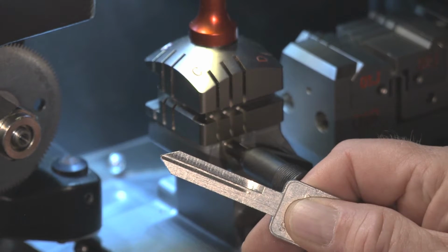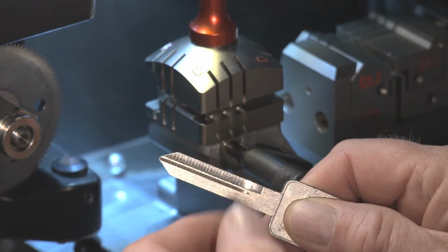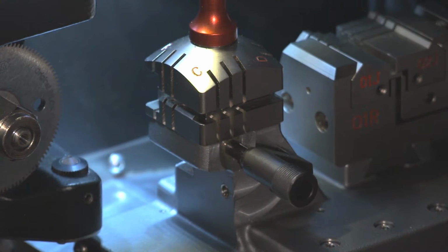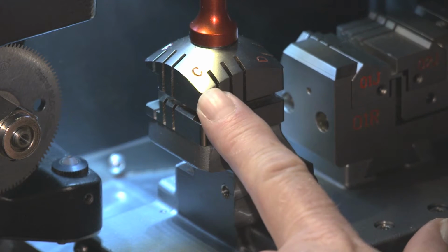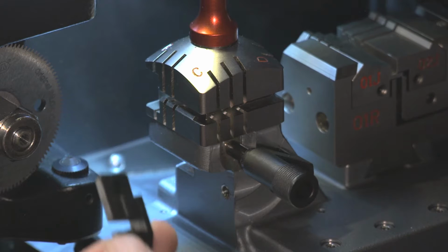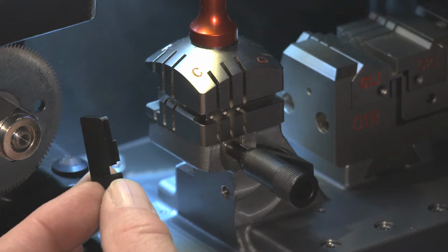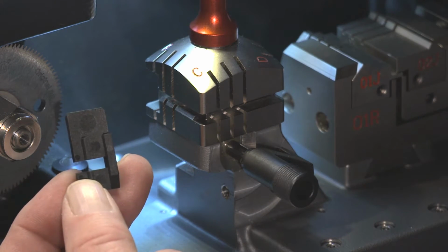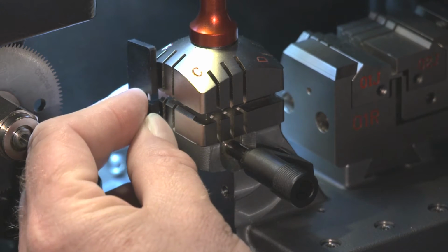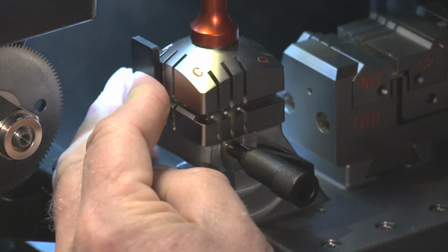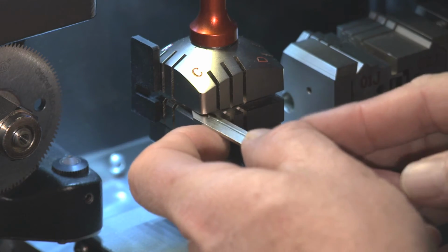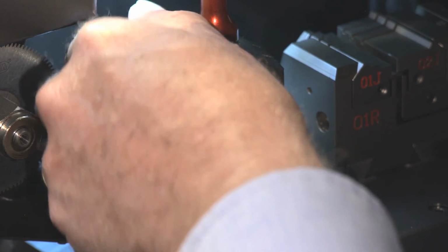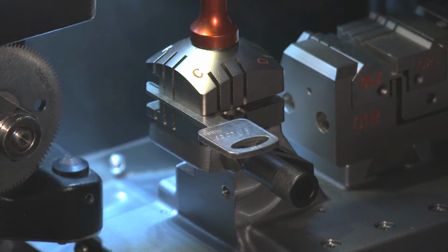Notice that with this particular key, the milling groove runs down the center of the blade on both sides, so I can use either side C or D. In this case, I will be using side C to clamp the key in the milling groove. Since this blank does not have a shoulder, it will be gauged using the tip of the key blade. The stop position shown is 4, located at the back of the clamp, so I will use the Stop 4 tool. Place the tool onto the clamp so that it fits into slot 3, allowing you to slide the key into the back side of the jaw, Stop 4. Remember to remove the stop tool before attempting to cut the key.